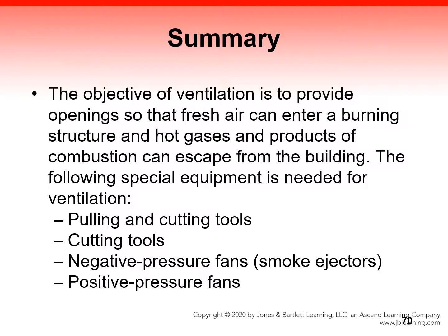The objective of ventilation is to provide openings so that fresh air can enter a burning structure and hot gases and products of combustion can escape from the building. The following special equipment is needed for ventilation: pulling and cutting tools, negative pressure fans called smoke ejectors, and positive pressure fans.